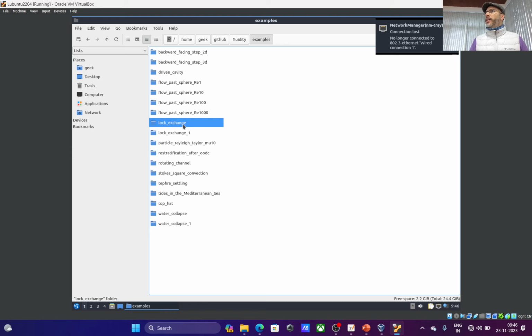A lock in this context is, let's say you have water used for canals, for example. In canals we have a gate. That gate is called a lock. So what happens is if you enable the lock, the water on the different sides can be of different heights. This is used typically when you have canals at different heights. So you have two locks. The water level is the same as, let's say, the left. And then if the boat has to go down to the lower level, the locks are closed, the water level goes down, the boat goes down, and then this is opened, and it goes away. So this is how a lock works. But a lock is simply a gate between two water bodies.